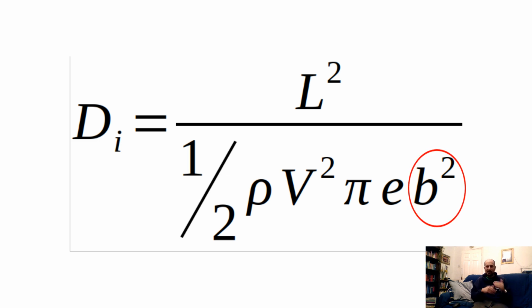But also there's a limit to how much we can push this bigger. In the case of a hang glider, really it's governed by the handling. So as we try to increase the wingspan and increase the aspect ratio too far, then you just lose out on the handling. So unless we can do something to improve the handling, we won't be able to increase the wingspan any further than we have at the moment. I will do another video on handling, because I do have some ideas there for how we can increase handling. There are some concepts there, but let's put that one to one side at the moment, and let's have a look at if there's anything else in this equation we can do.